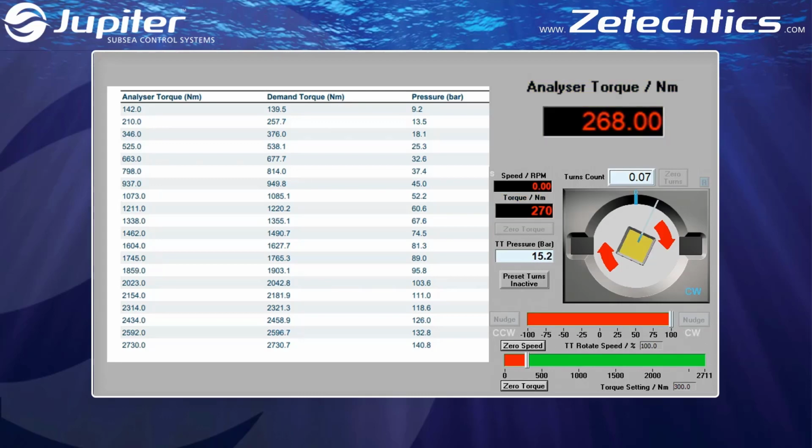Demonstrated next is an exaggerated example of a common error when operating. Notice how the flow slider jumps to the position clicked, then is dragged to 100%. As a result, the achieved torque is much less for the same pressure applied. The next example shows approximately 50% flow applied, and again less torque is achieved. In both of these examples, the torque feedback is comparable to the analyzer.